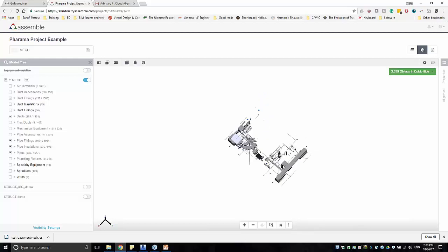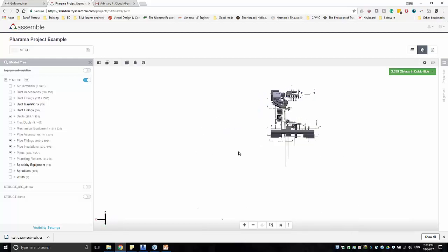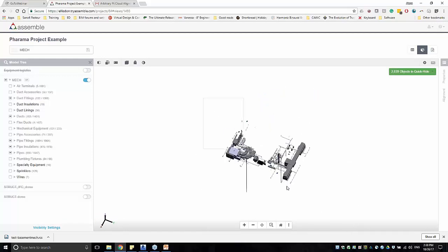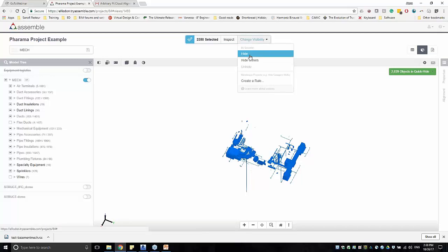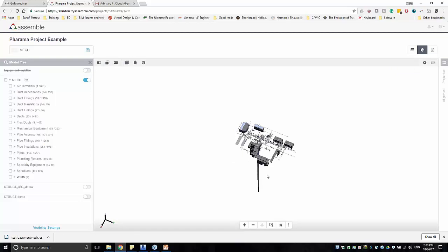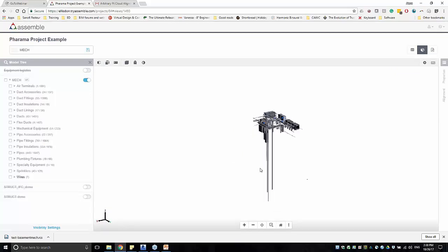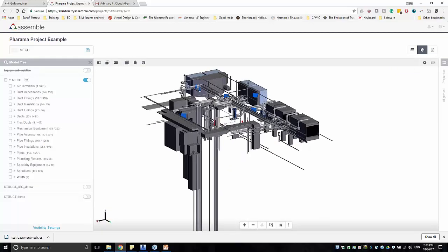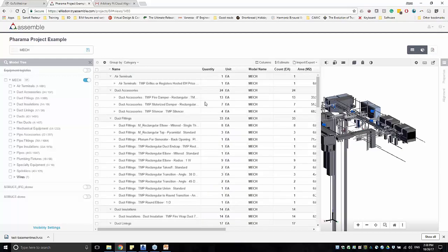So this, now let's say, this is me again. Let's say I only selected things I wanted to keep. What I want to keep is under the quick hide. So I select everything else, I change my visibility, and I hide what's still visible. Once that happens, everything I had quick hidden is now the only thing left on the screen. And because I made it quote unquote permanent, this is also updated to only match what's visible on the screen. So I really like that feature.